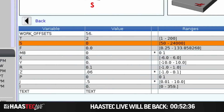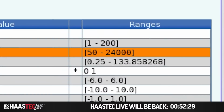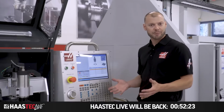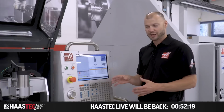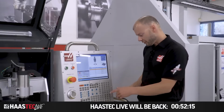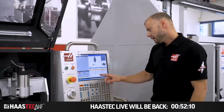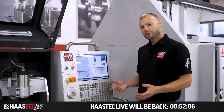Now it's asking for my spindle speed. How fast do we want the cutter to turn? I have a valid range of 50 to 24,000, so quite a bit of range in there. I'm going to choose 5,000 RPM just from my experience. And I know that that won't be too fast for this machine. Since we don't have coolant, I don't want to melt the plastic, so I'm going to select 5,000 and press enter. Next, I need to give it a feed rate. How fast do we want to move? Well, how do we calculate that?